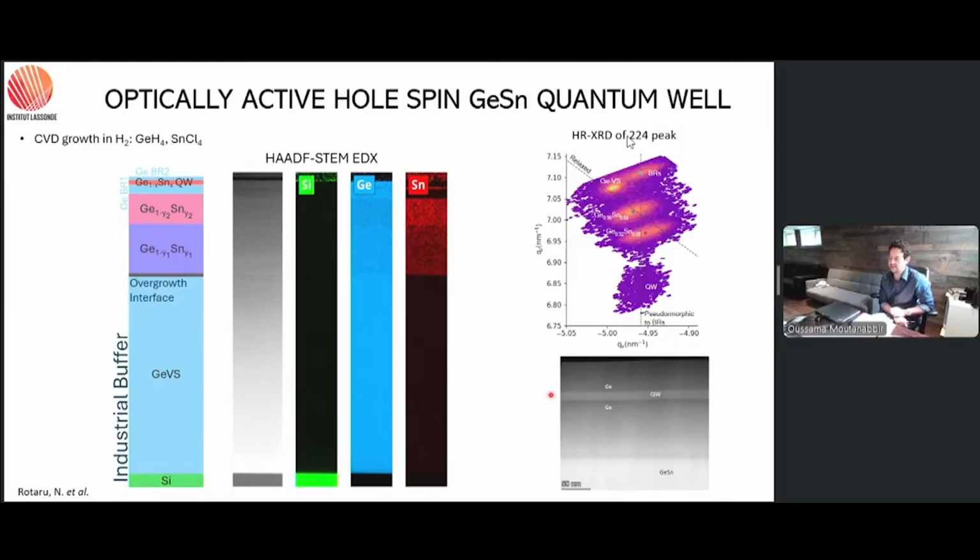Certainly. Putting on just the materials hat, one of the major challenges with this material system is that we have to establish everything from scratch. There is nothing we can build on in terms of how you make the contact, or how you make sure that what you are measuring is not something other than the transport in the quantum well. You have to deal with background doping, because these materials are grown at relatively low temperature.